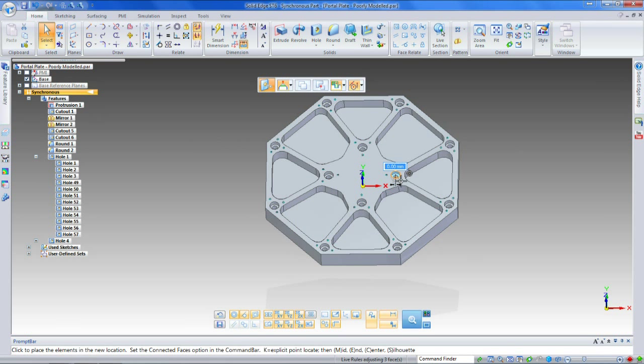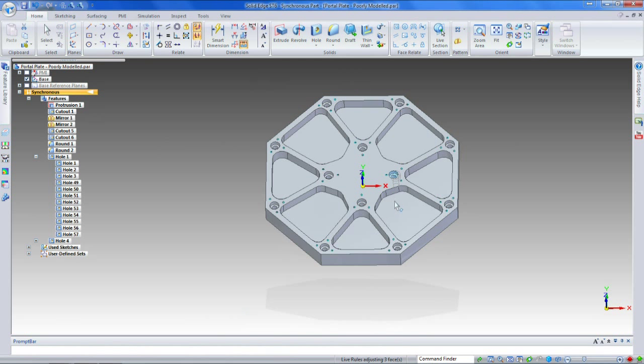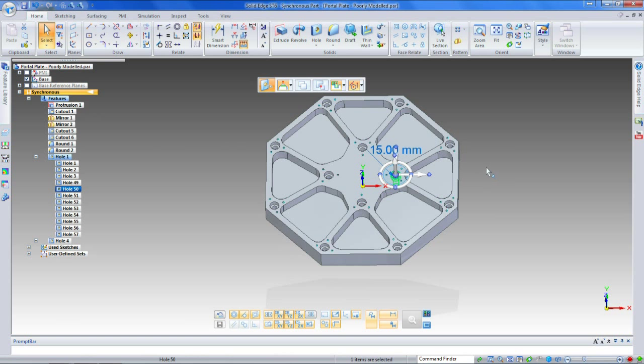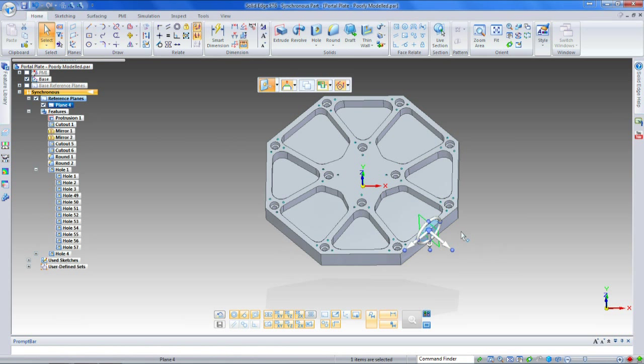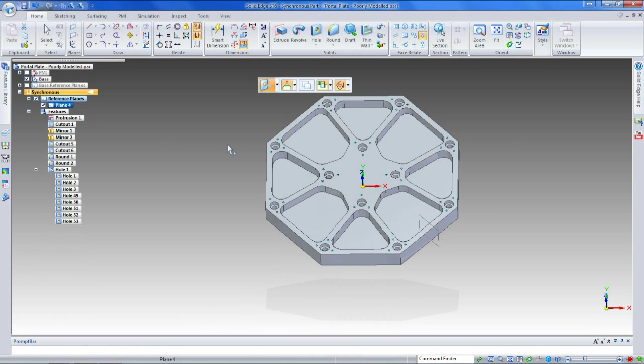However, if the part is not correctly modelled, for example with that hole, then you may not get a symmetry detected. So what we want to do is fix up this model so we can edit it and make any changes we want. First thing I'll do is create a base plane, and then I'm going to ground that base plane so it cannot move.